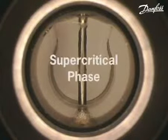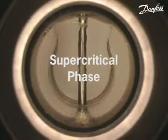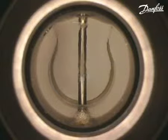This supercritical CO2 has some interesting and user-friendly properties. Its high density gives it some of the properties of a liquid, so for example it can act as a solvent for extracting various materials. However, its viscosity is much lower than for most liquids, and its diffusivity is consequently higher. These properties have led to a great deal of interest in the use of supercritical CO2 as a safe, effective solvent, in particular for food products.